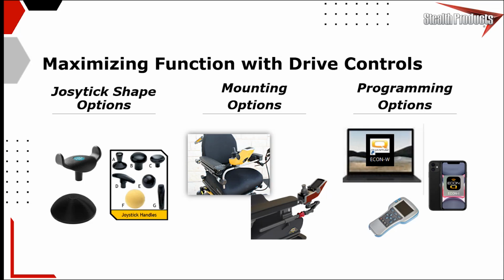And these days there's programming inside of almost every drive control itself on top of what the chair has. And that can really help us be much, much more successful. If I have a great forward throw physically, but my left and right is kind of a struggle, I might be able to just reduce the programmed throw requirement so that that client reaches that full turn with a lot less movement from the joystick, right?